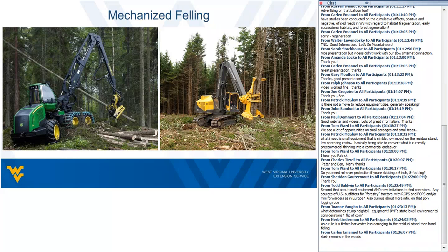Okay, then we have a question about rollover protection. You were talking about some of the smaller scale equipment, and there's a specific question about size and length of logs, but in general, is rollover protection something you can ignore if you're working with smaller sized logs, or is it something you need to be attentive to regardless? If you're moving equipment in the woods, do you need to be attentive irrespective of log size?